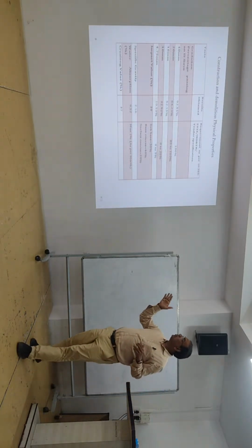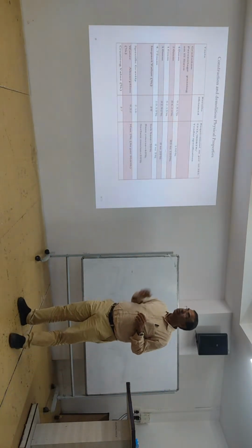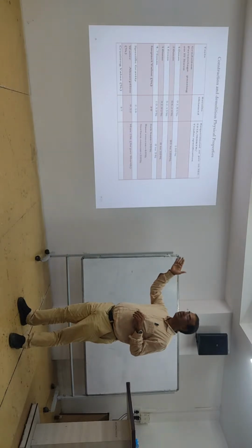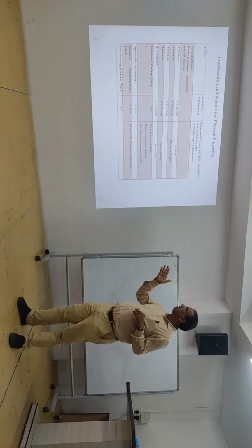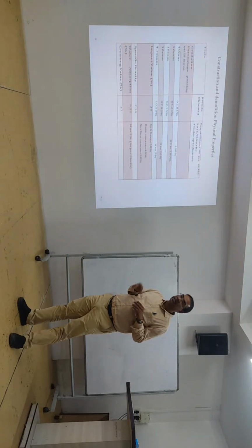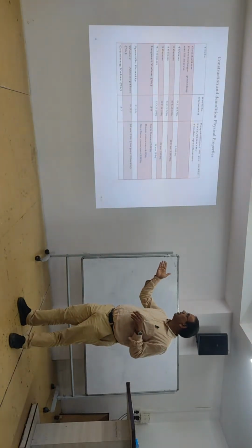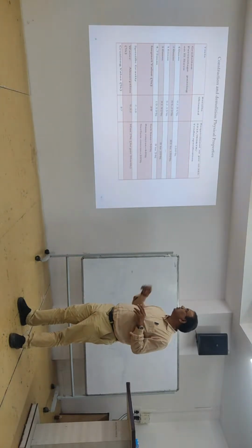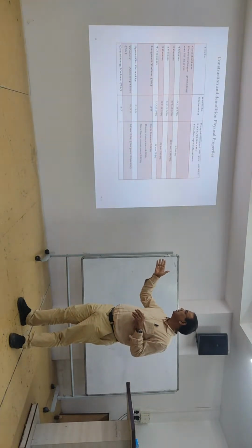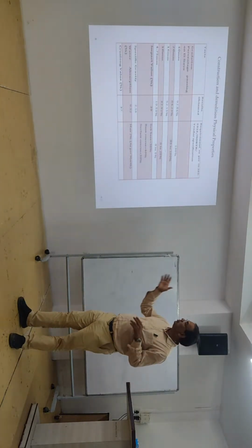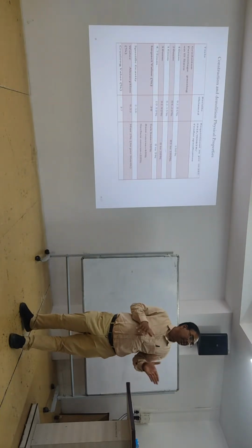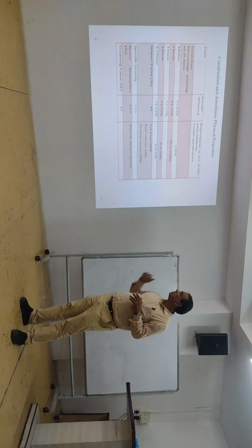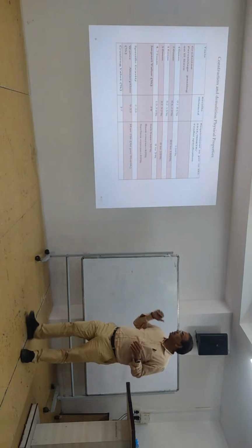So this is the physical form of the construction and demolition waste that we get here. Aggregate of 40 mm size, 20 mm size, 16 mm size, 4.75 mm size. Impact value also you can see we are getting 39. So sub base 50%, 40%, subsurface is less than 30%. So we can see that sub base and base course we can use as per present guideline this same waste. Other parameters are given.